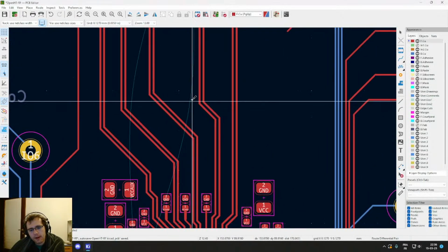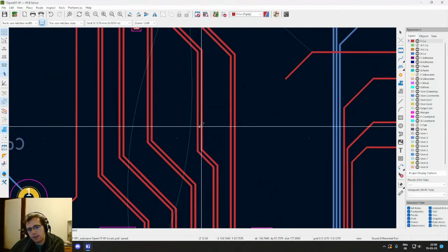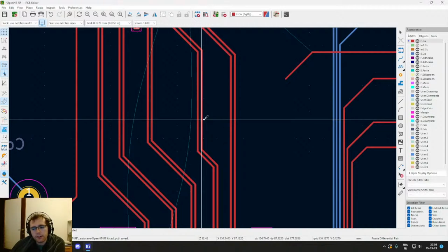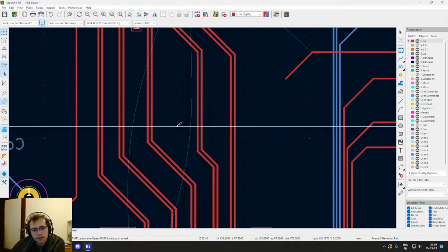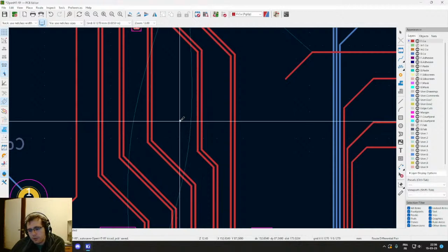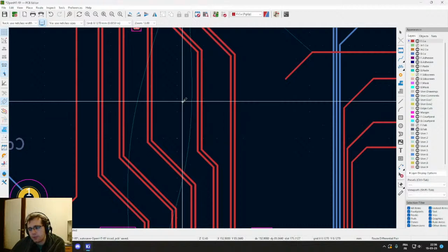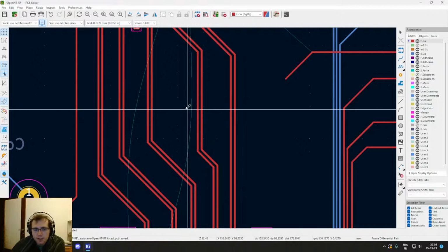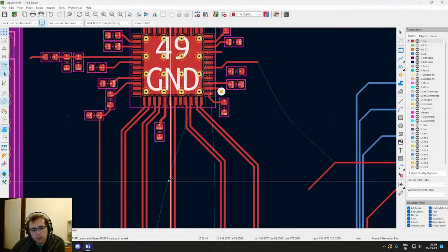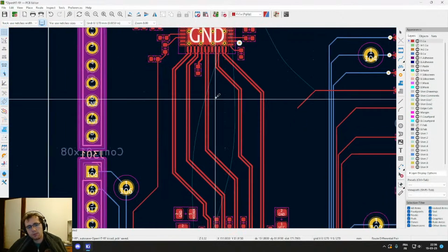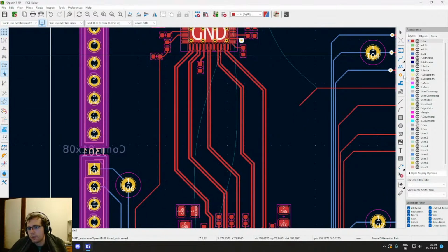When you have high frequency, it's gonna create inductive current, eddy currents on the sides, and if we want the reference on the sides to be stable at a solid 0 volts, then we need to put plenty of vias around, which are gonna be stitching, if you want. So we can maybe do a small example here.